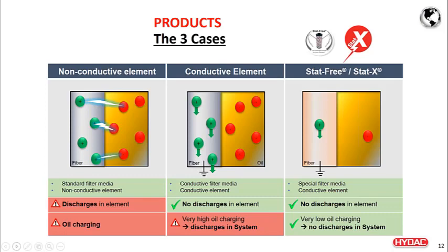And that charge in the oil can only be mitigated if you have a filter element that is compatible with that oil, so that it doesn't exchange ions and doesn't get charged. And that's what HYDAC's stat-free and StatX are doing. So stat-free and StatX elements are compatible with the oils and not exchanging any ions, getting less to no charge in the oil as well as in the filter element. And hence you have very safe operating conditions.